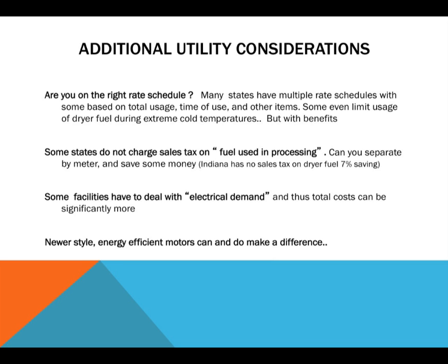So if you go out and start up your legs, and you start up your conveyors, you start up your dryer, you go to load, you do all that stuff, and you pull in 1,200 horsepower. There's a peak that the utility sees and it says, that's how much you want to use, you're going to pay for it. Okay? So you could be on a demand. And I'm sure if you're looking at your utility bills, you probably already know that. But just be aware that it could have a major dramatic impact on your cost as well.